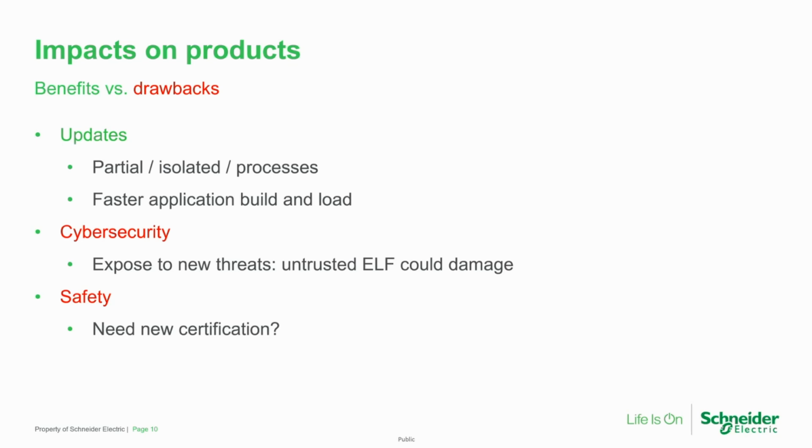But there are drawbacks, as the previous presenter said. With LLEXT, if you put some code onto your device, it means someone can actually tamper with your firmware. That's definitely not what you want. So you have to add some kind of security with private keys and secure keys, like the previous speaker said, when you do a trusted firmware and you have a first secure boot, a second boot, and then a secure application, then you have to find a way to have a secure extension.